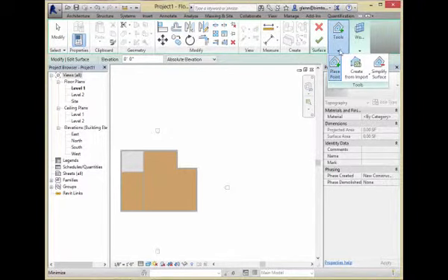Turns out there's a couple of ways to create a topo surface. You can create a topo surface by placing points where you're just specifying individual elevations of how high the ground should be. And sometimes I do that by tracing a topo map. That's a really good way to do it. Another great way to do it is create it from import.